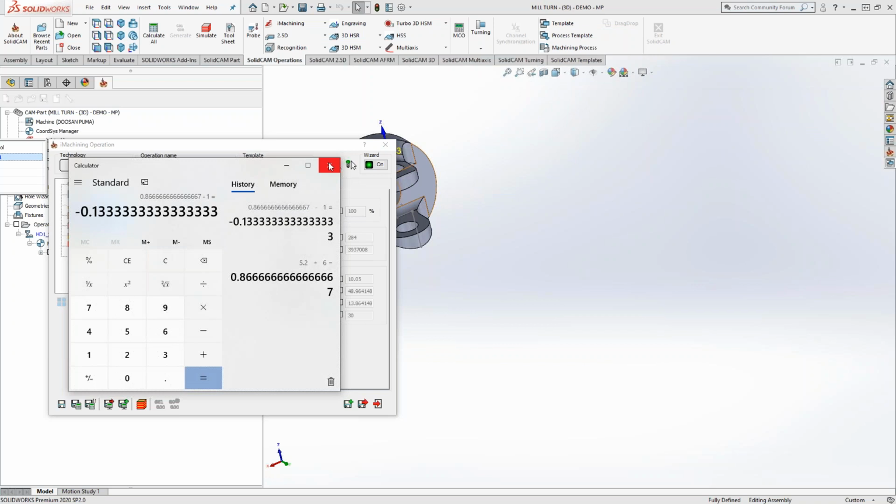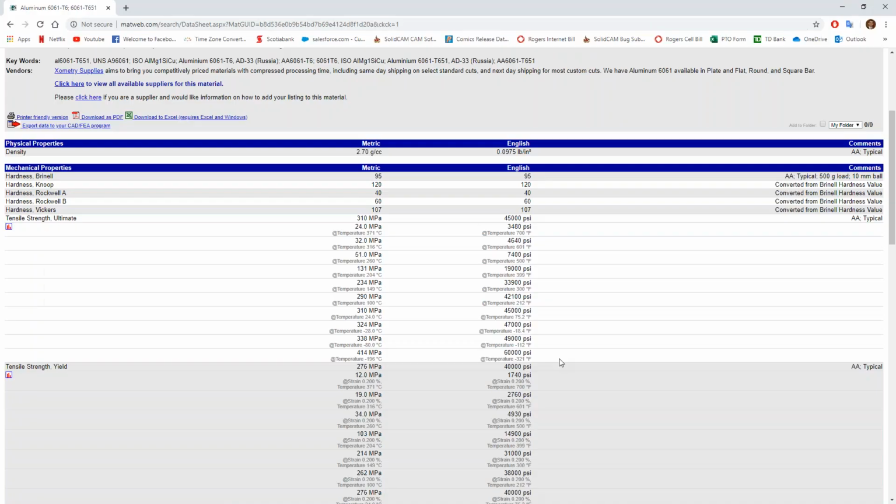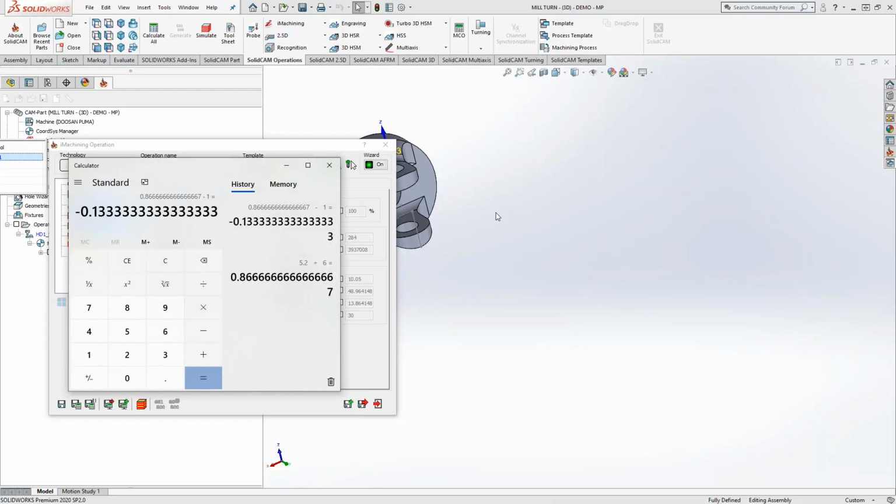Now, chances are you're probably okay with the number you plug in for your ultimate tensile strength. It's more for, like Kevin said, maybe it's a different supplier, maybe it's not 100% 6061, maybe it is, but like you saw on the other screen, let me just bring that up. Sometimes that value does change per the temperature, or maybe in other materials it's annealed versus work hardened, or other scenarios where it is that same material, but some sort of circumstance has made it harder or softer. So a lot of that plays into this optimization.